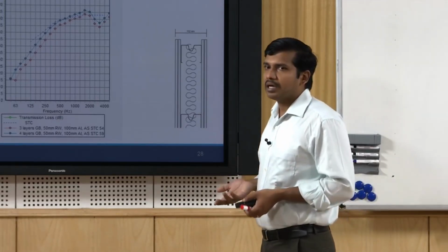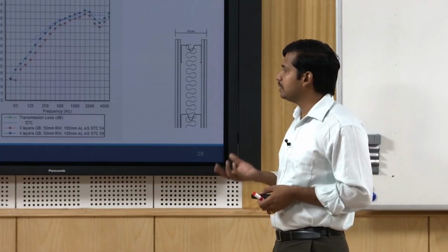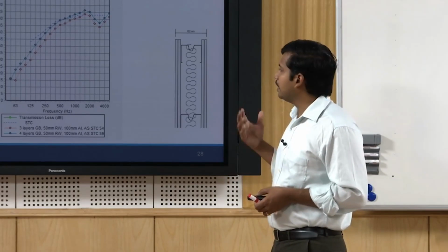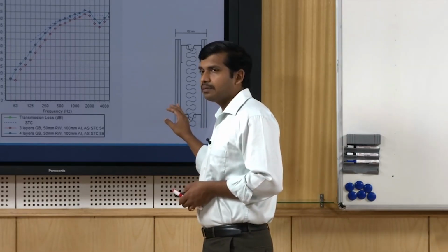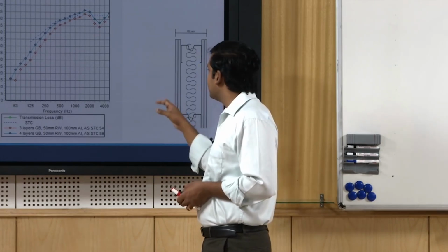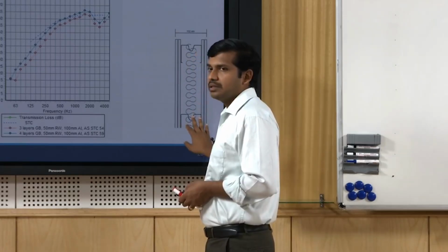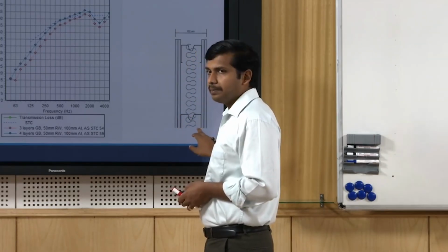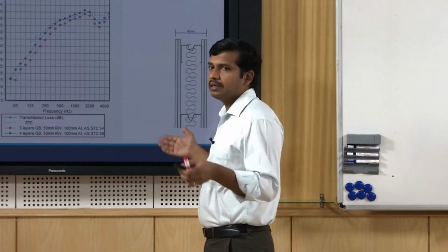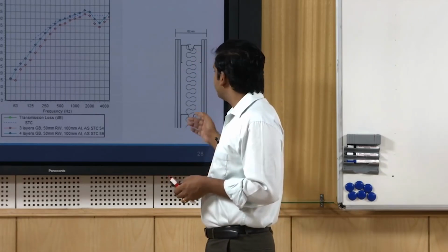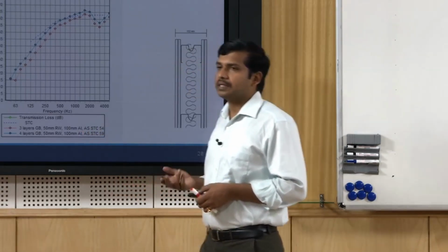So typically you have to understand, as the STC requirement increases, higher STCs are essential. There are various strategies like going in for thicker panels, adding another board, 2-3 boards, or introducing an air cavity, introducing insulation material, changing the stud types, or adding panels on both sides, increasing the total air cavity. Depending on these things, you can attain an improvement in terms of STC.